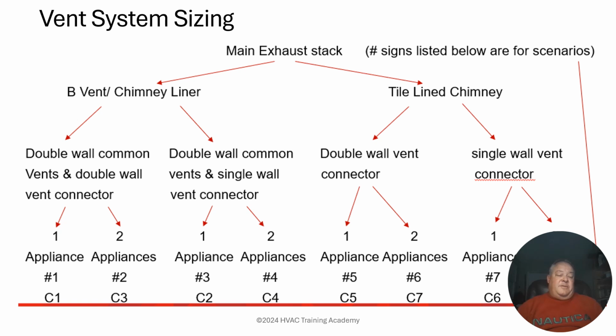It's whether they have double wall vent connectors, or B vent connectors, or single wall or C vent connectors. They're very different because even though the diameter is the same between those two materials, double wall vent or B vent keeps much more heat in the venting system and exhausts much more of it on out through the double wall common vent to the outdoors.